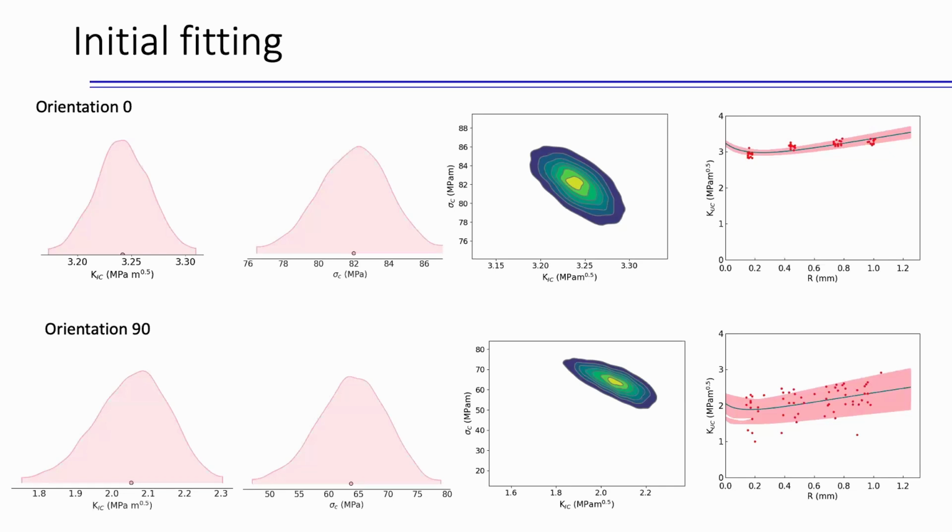In this plot, we can see that we have a great dispersion with the notch stress intensity factor, and this is a methodology to quantify this dispersion of the toughness. The procedure gives us more information because it gives us information about the other parameters. In this methodology, we have two parameters. One is the toughness, that is, a notch radius with radius 0, and the other is the maximum stress.